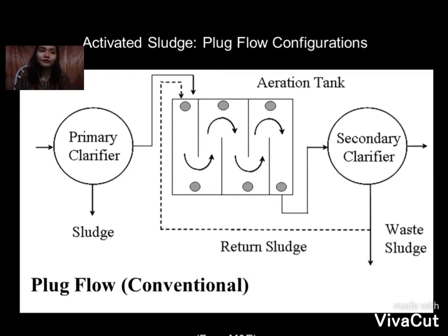The process of conventional plug flow. When the settled wastewater and recycled sludge enter the head end of the aeration tank, air application is generally uniform throughout the tank length. So during this aeration period, the adsorption, flocculation, and oxidation of organic matter occurs.